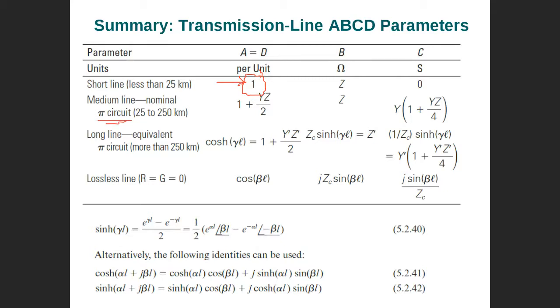These are from 25 to 250 kilometers. So in the problem statement, you need to look at the length. Can I use a medium transmission line? Can I use the long transmission line equations to solve a medium transmission line? Yes. It will give you more accuracy. But is it worth it or not? It depends on the length. But it will give you more accuracy.